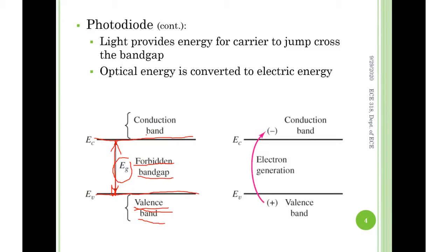So you can imagine the bigger the band gap is, the more energy is required for this semiconductor to become conducting current, right? If from here you jump over the gap to here, it requires how much energy? It's all up to how much the band gap is. Does that make sense? This is the model, a very popular energy model.